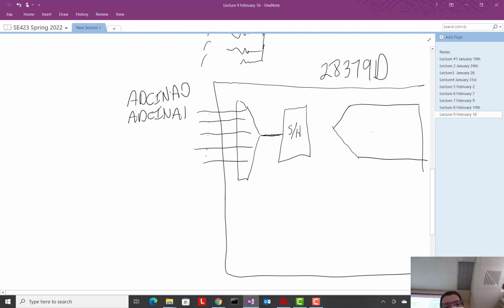So let's just say we've selected ADCIN 0, the one that's switched in there. For our example, let's say that's 1.2 volts coming into that pin. There could be different voltages coming into the other channels, from different sensors. There are a lot of sensors that give out an analog voltage. The little photoresistor you're working with in homework 2 gives an analog voltage. The joystick you just took, if you didn't get one after class, also gives an analog voltage. So that voltage comes through here.